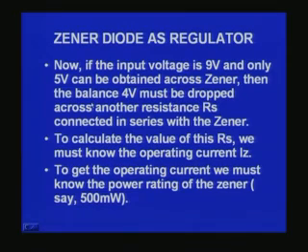So whenever a Zener diode is used in the breakdown region, you must have a series resistor Rs, which is used to bias the Zener diode and to drop the excess voltage available over and above the breakdown voltage. Now, how do we calculate the value of Rs in a given situation?